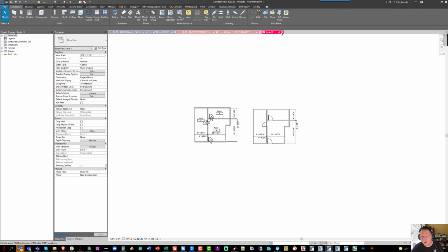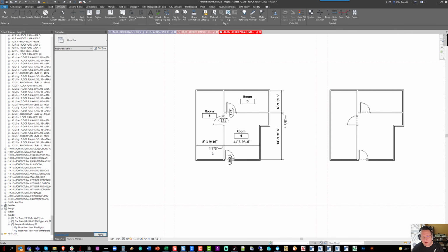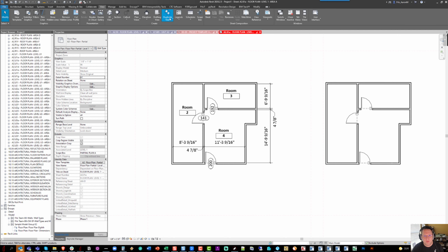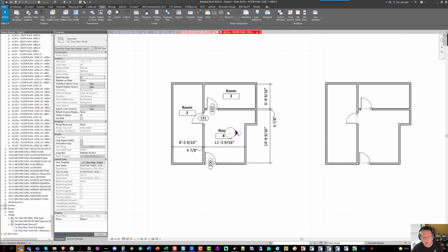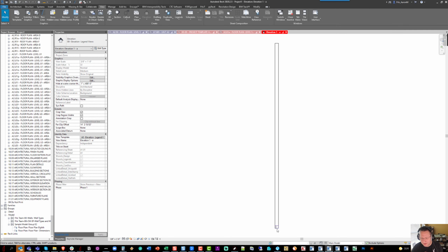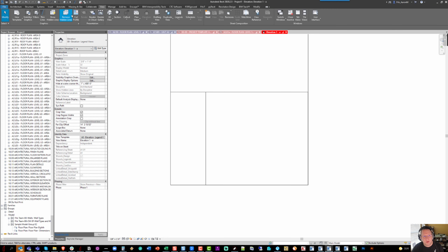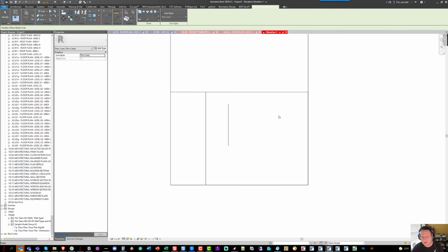So it's also important to note, I'm going to close that sample file and go back to the project where we created our group, that these things don't all have to be, of course, in floor plan or in reflected ceiling plan. If we were to place an interior elevation in one of the rooms, and go to that elevation, which will have almost nothing in it because I haven't actually modeled anything in here, you can even put detail lines and dimensions for things in this view.